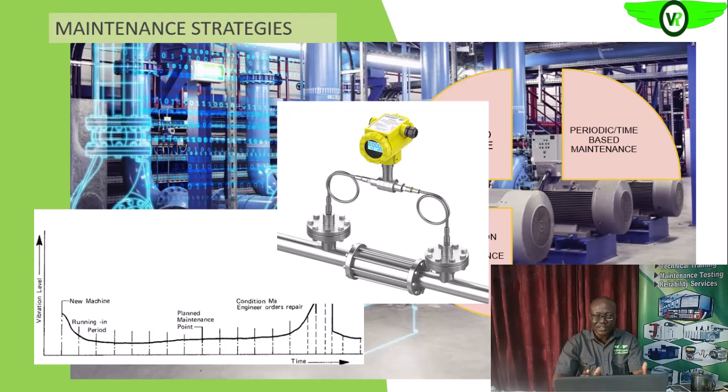Okay, are we getting it? So once it's getting clogged, definitely that will increase the delta P, which means that more restriction is now exerted on the flow or on the suction line through the filter. So if the filter is clean, you see delta P will be low, which means that the resistance to flow through the filter is reduced. So these are some of the parameters that we can look at to give us the condition of those important components of our plant equipment or of our process. So when we talk about condition monitoring, that is what we are actually looking at.